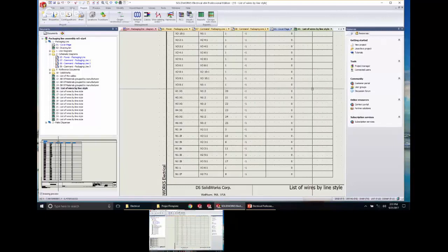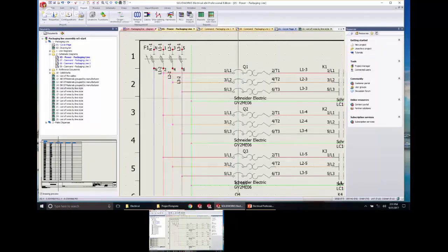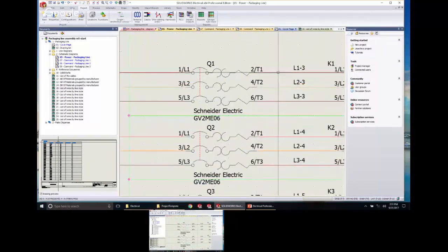And if this wasn't a SQL database based program, yes, you could. But this information, remember, anything on these reports, it's all reading it from somewhere. So it's not like an Excel table where you can just go in and change that. So how you would change it is you'd go to the physical wire here. Let's say this L3, right?